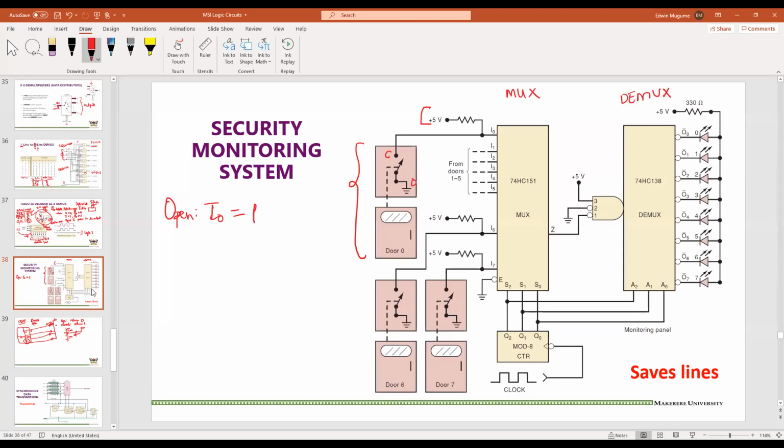So really the signal going in there is 1. That means the Z out of the multiplexer is 0. You can see that that is Z inverse. This multiplexer 151 gives us the normal output and its inverse. You should go back and see if you are confused by that. Now, this 0 goes into here.